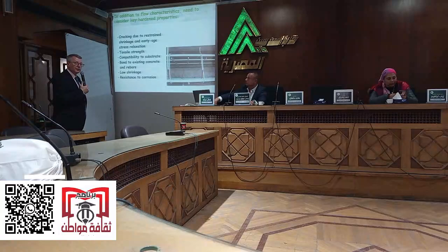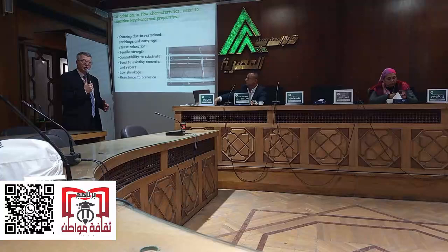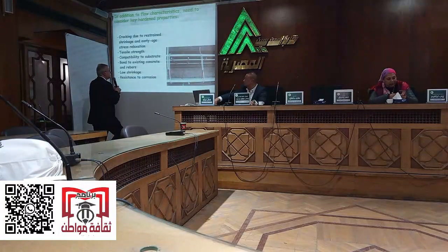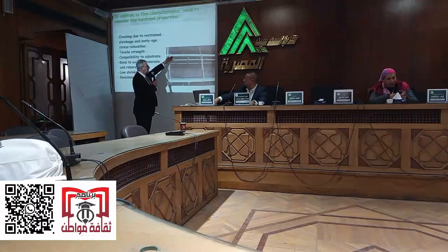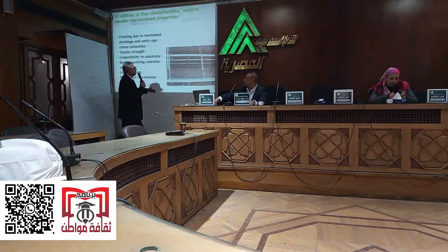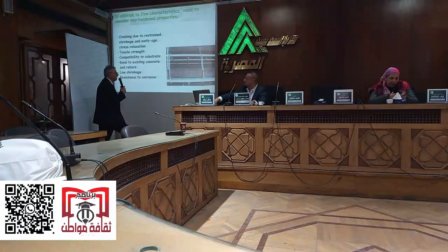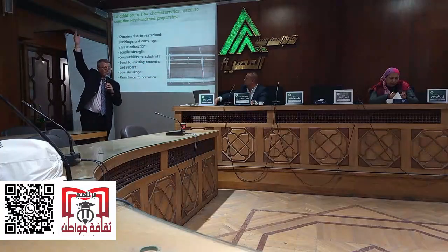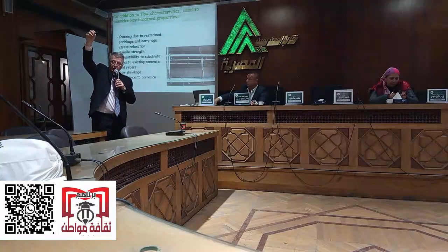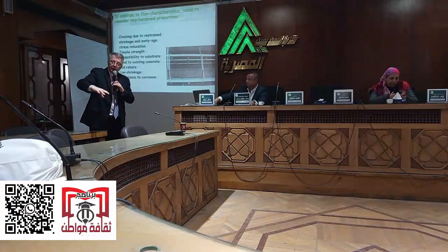Okay, let's go back to use of this beautiful material SCC for repair. Again, I showed you why it's used in repair, because you have areas that are very restricted. This thickness here is usually 50 millimeter, 75 millimeter. You want always to have some space behind the rebars to anchor the repair. And it's going to be restricted, and you can be repairing a wall that is 7 meters in height. Again, you drop it, you put a tremie or a pipeline, and you pull it slowly, and you fill the formwork.